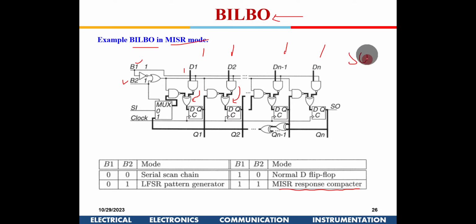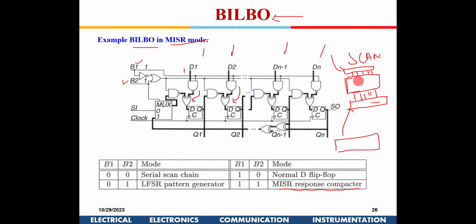The beauty of the scan design is that today everything is in a pipeline structure, right? So every combinational block is connected from a set of flip-flops to a set of flip-flops. Hence the testing has become very simple, because you are independently able to put data into these flip-flops and capture this data. Unlike in the earlier days, if it is not a pipelined structure, you have combinational blocks connected to each other, and then it becomes very complex.